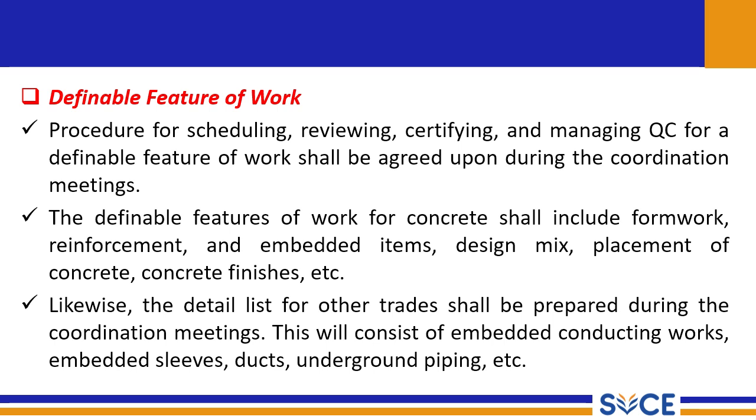Definable feature of work. The procedure for scheduling, reviewing, certifying, and managing QC for a definable feature of work shall be agreed upon during the coordination meetings. A definable feature of work for concrete shall include formwork, reinforcement, and embedded items, design mix, placement of concrete, finishes, etc. Likewise, the detailed list for other trades shall be prepared during the coordination meetings.